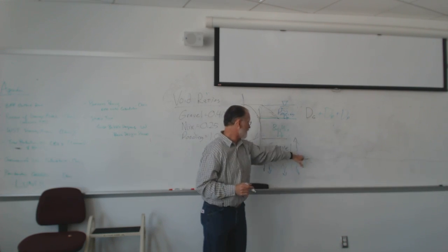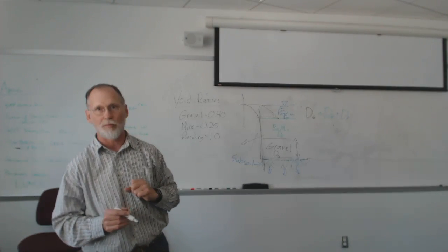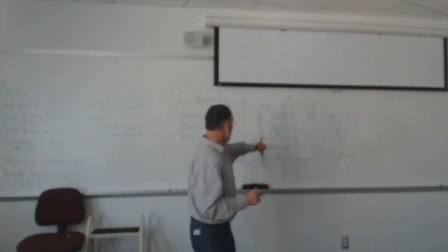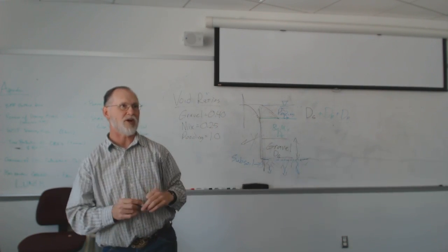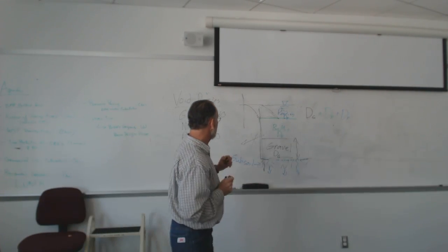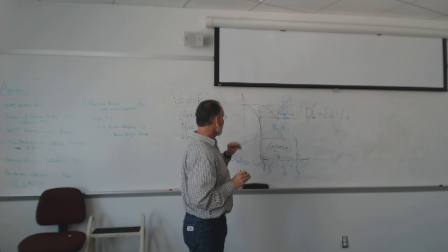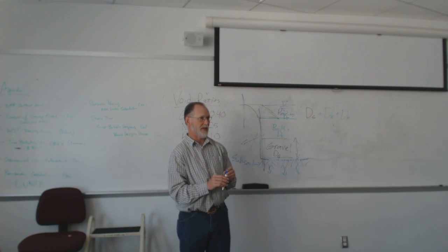I never, ever have anything where my subsoil has got any slope at all. Dead flat, dead flat, dead flat, all the way across. Now in reality, your rain garden mix is going to settle and you'll end up with a little lumpy stuff, but essentially it's all the same elevation. So I want to figure out how much volume I can get in this rain garden.